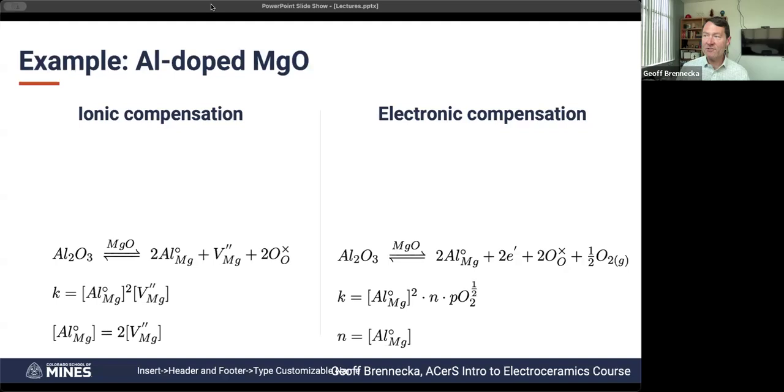Can you increase oxygen interstitial concentration with quenching? It's not just the oxygen interstitial concentration you can increase with quenching. All of these defects are going to have, well, almost always, the defect concentration is going to be higher at higher temperatures, just because there's more energy available. So you've got more possibility of energetic things happening. So that's true of Schottky defects, that's true of Frenkel defects, and it's a little bit less true for these kinds of doping situations, because I mentioned before that this example where you could actually drive the reaction back and forth by changing the PO2.